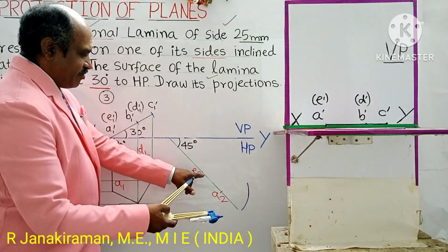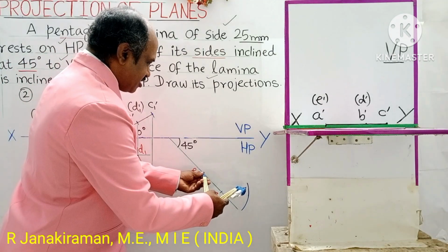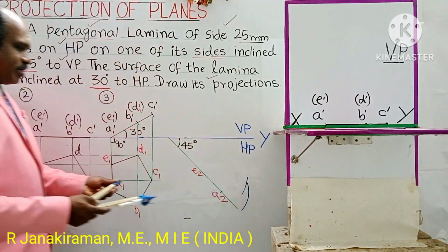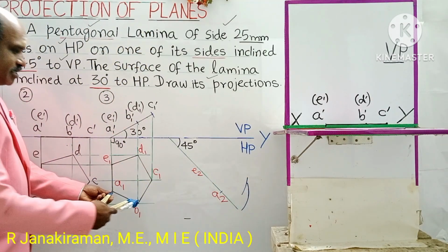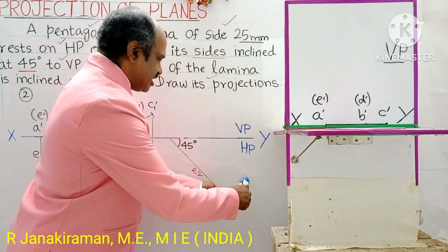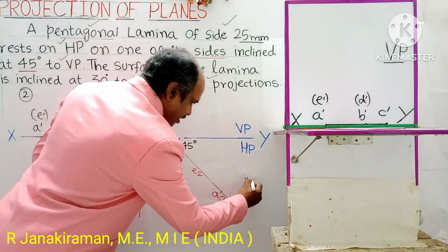Here is our E. Whatever point you took from here, copy paste the same here. Both arcs intersect here. Again I'll repeat, the A1, B1 distance is taken in the compass from A. Extend this arc. Both arcs intersect here, shall be marked as B2.